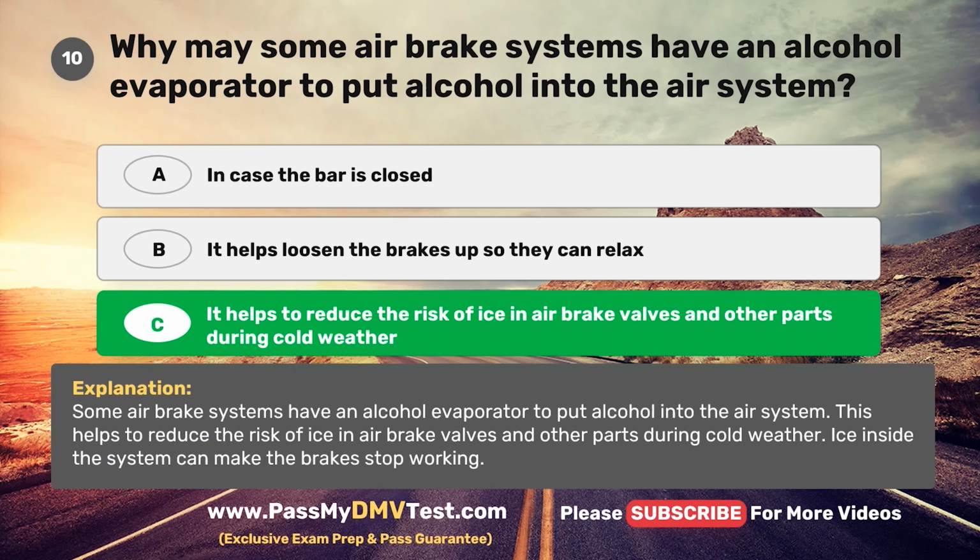Some air brake systems have an alcohol evaporator to put alcohol into the air system. This helps to reduce the risk of ice in air brake valves and other parts during cold weather. Ice inside the system can make the brakes stop working.